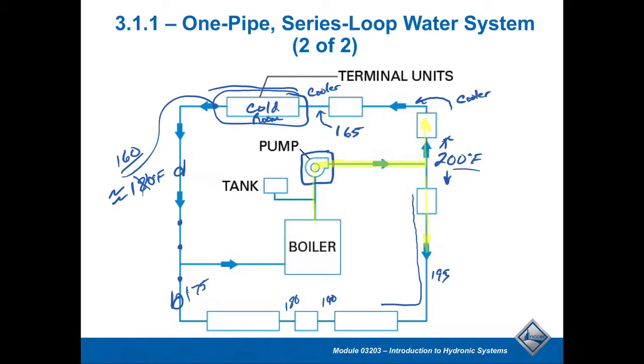So what's going to happen is there'll have to be a balance valve on the return side of each of these loops. That would be ideal. The balancing valve is going to allow me to tweak that side that is the warmer of the sides, this one.